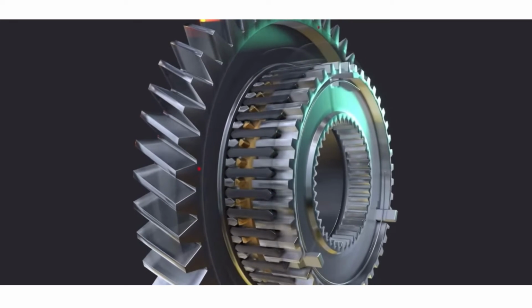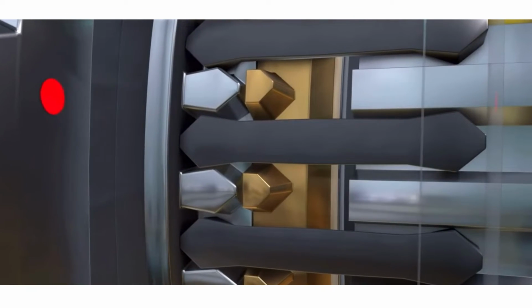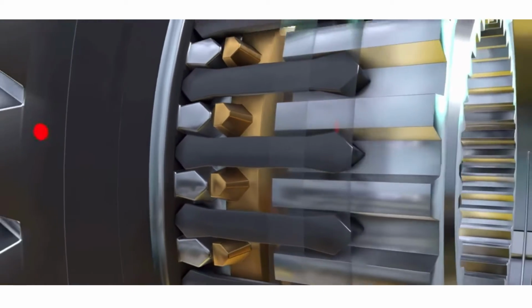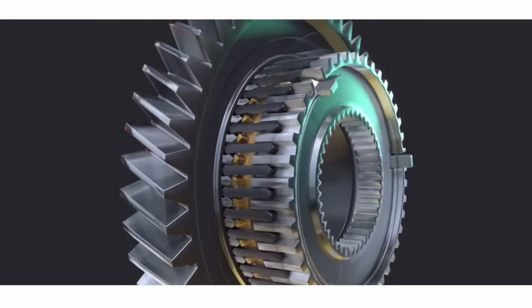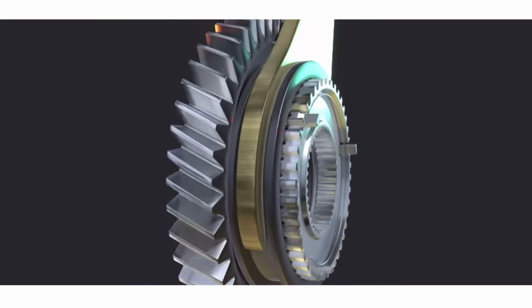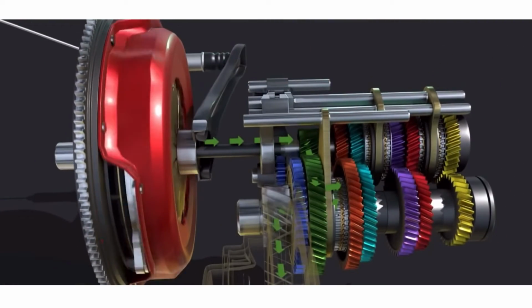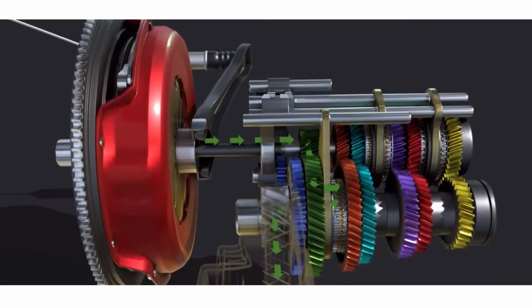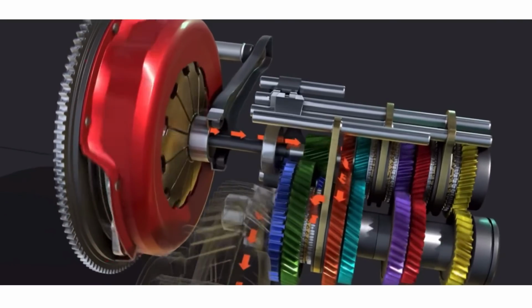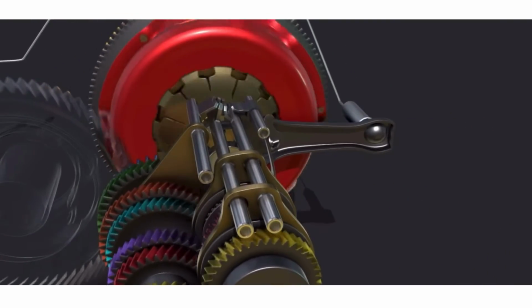3. Synchromesh gearbox. This is the latest type of gearbox, used for decades, as this system overcomes all the limitations provided by the constant mesh gearbox or sliding mesh gearbox, and also improves the output capabilities of the manual transmission system. In this type, the dog clutches from the constant mesh gearbox are replaced by synchromesh devices, which first bring the main shaft and lay shaft to the same speed by frictional contact.